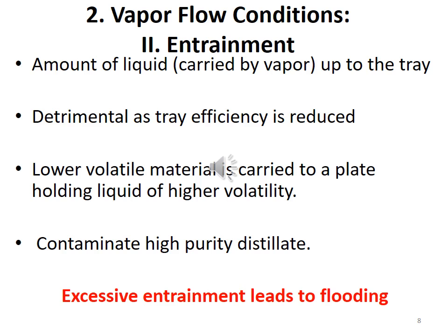But this process of entrainment, which occurs by carrying a liquid by the vapors, is detrimental because tray efficiency of separation is reduced. And this is because lower volatile material is carried to the plate holding liquid of higher volatility and gets mixed to create a mixture of different components with different volatility.